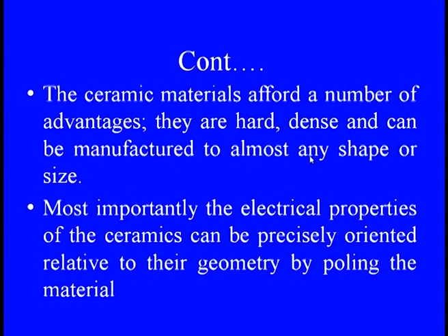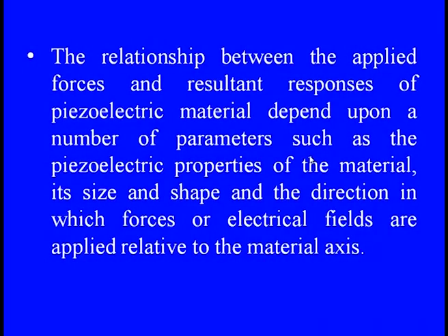So ceramic materials afford various advantages which we discussed, and they can provide whatever electric properties are required. The relationship between the applied force and the resultant response can be obtained immediately using the appropriate properties of the piezoelectric material, its size and shape, and the direction of the applied forces, or the direction where the electric fields are generated relative to the material axis. This is one of the beauties here: when we apply these relations in a real application, we can immediately see what exactly the requirement is and how we can generate the amount of charge, or sense the forces when the voltage drops.